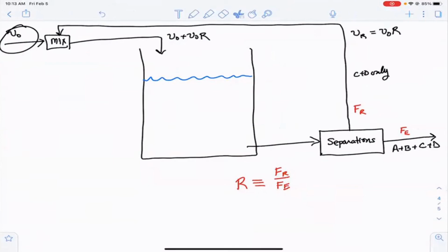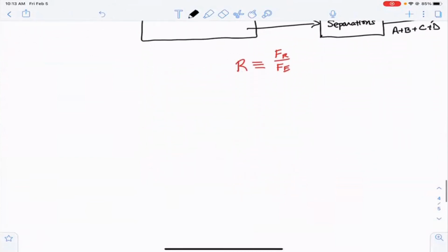So hopefully what we can do now is a mole balance on the CSTR and try to see how this gets implemented into boosting the conversion. Okay, so let's do this. Let's take this concept and apply our CSTR equation. Remember, for a CSTR, we're operating at steady state. So this is just in minus out plus generation minus consumption equals accumulation.